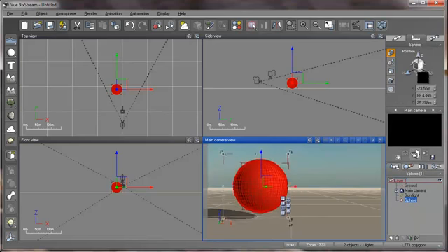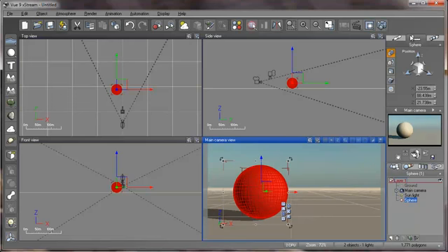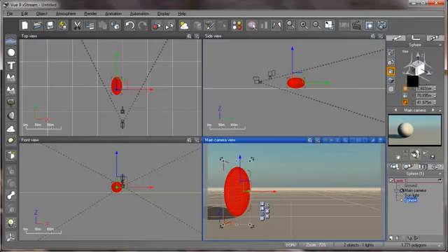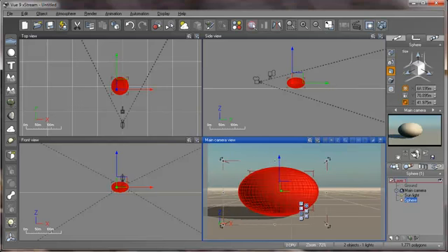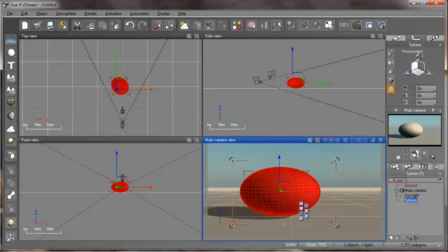You can move it like this automatically without going to the viewport. Here for example the orientation, here the size, you can drop it like this, or as you want, you can move it. Now this one is the twist, if you want to rotate it. And here is editing the position of the pivot point.